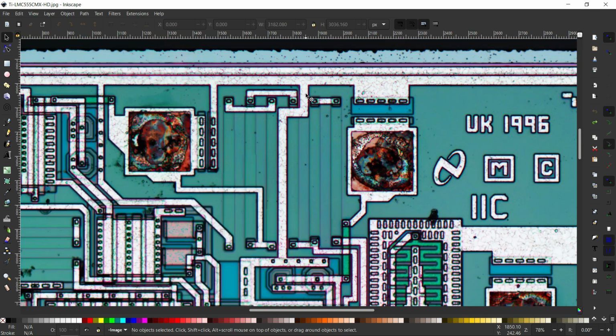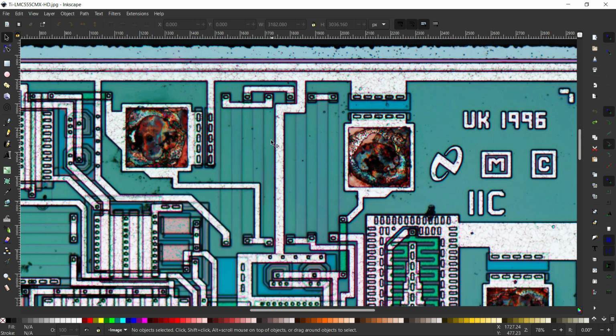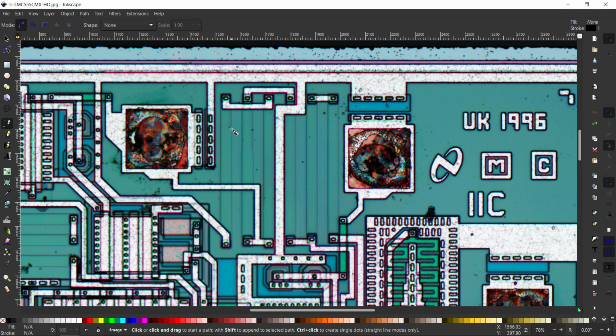So let me start from the beginning here. Whatever you are seeing here in the straight line, these are all a resistor divider, because we have already discussed in our previous diagram, it has 3 resistors R1, R2, R3. Each resistor consists of 5k value. Let me show you how the resistors are laid out here, and I will show you the resistor pattern matching and how they have structured the design.